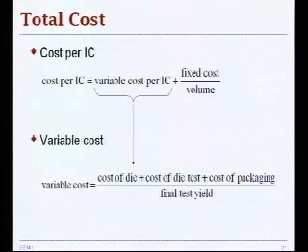So you have to discard those malfunctioning dies and account for that in your variable cost as well. So what this expression tells you is that for large volume products, you have basically averaging out of this fixed cost, and so the goal is now to reduce this variable cost as well in order to minimize the total cost per integrated circuit. Questions? Everything clear?